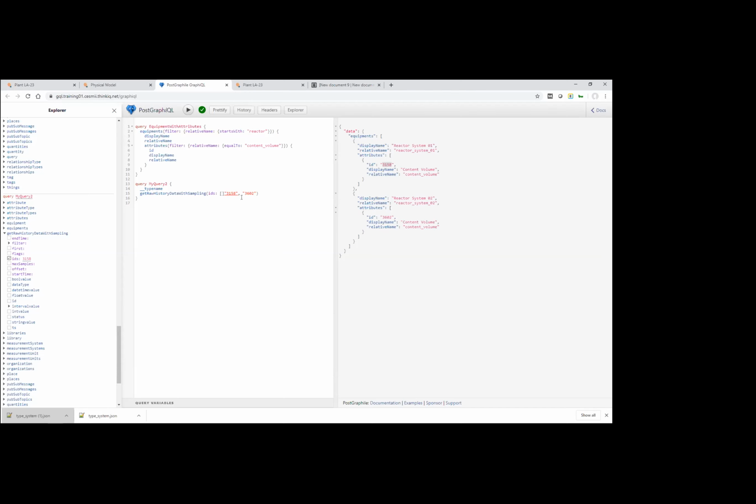And then I also need to define the start time and the end time, and I need to define how many value points I need to get, the maximum number of value points, max samples. And I need to define what data I want to get back. I want the timestamp back, a float value back, and I want the status, the OPC UA status code, and the ID of the attribute I looked at.